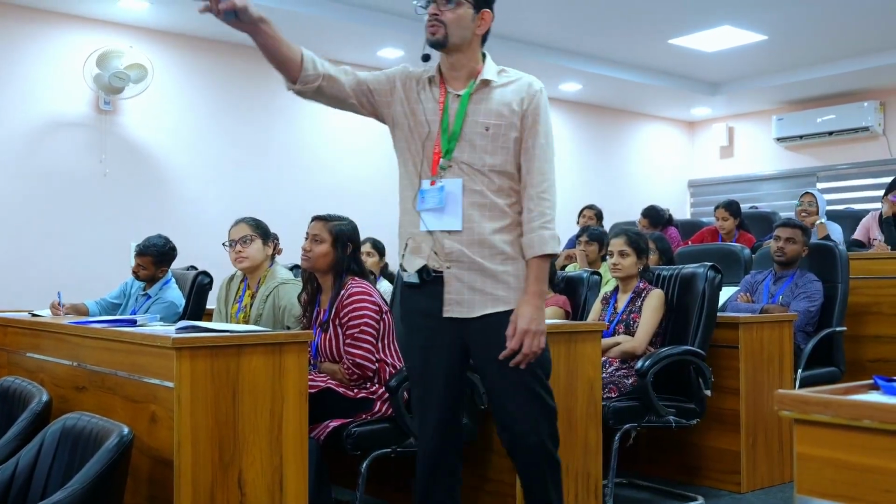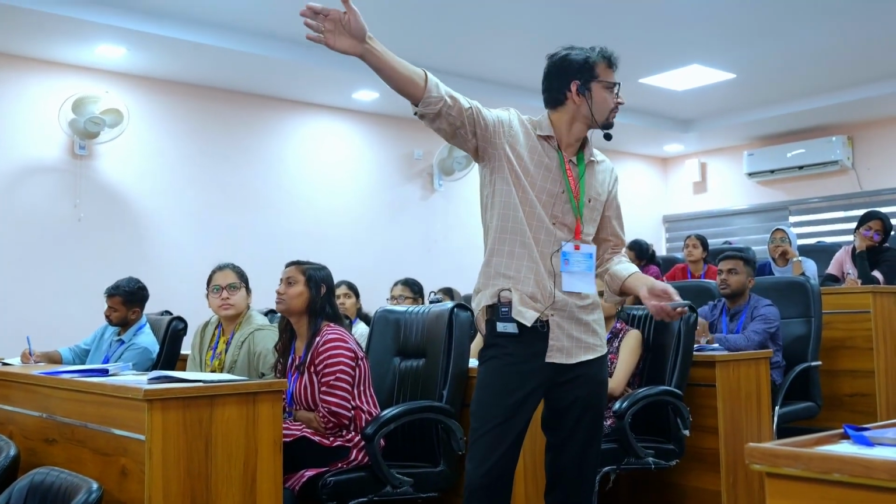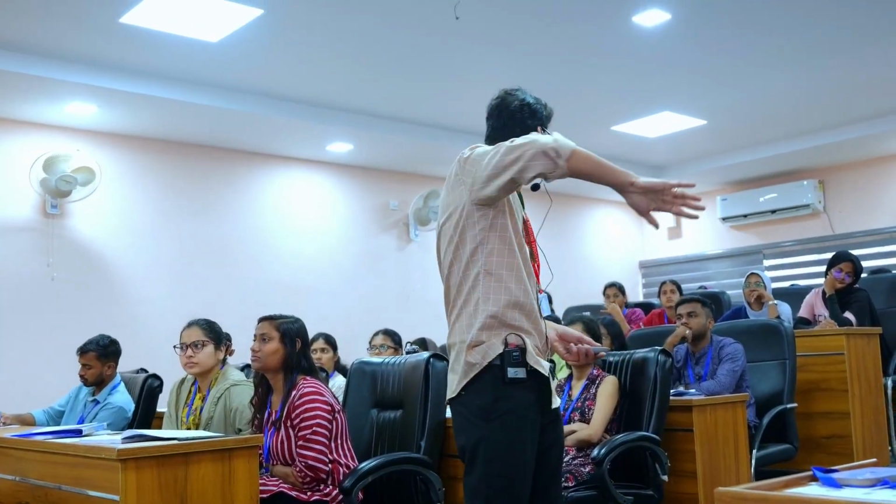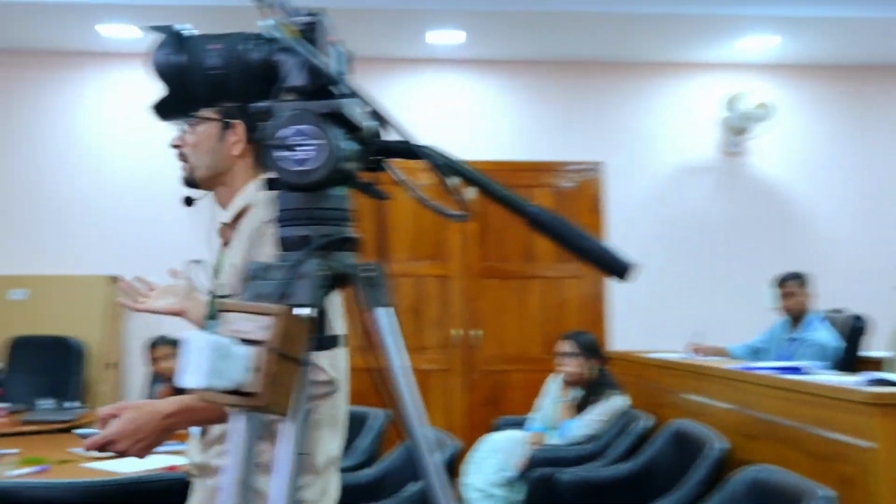In this setup you can actually do everything. You can add water and see how the contact angle varies, measuring the advancing and receding angles, or you can tilt the surface. We will be doing both of these experiments in the lab today. Some groups will be doing them today, and by the end of your course, everyone will have done this. So advancing, receding, even surface tension, you can measure.